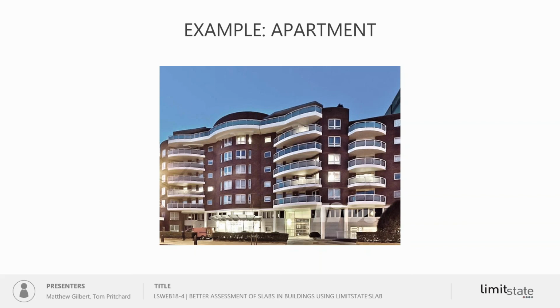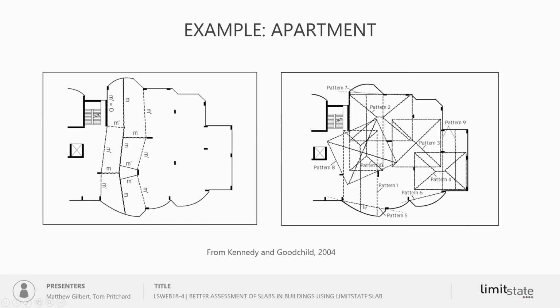And then the last example I'm going to consider is one that was actually considered in the Concrete Centre guide on yield line design some years ago, I think 2004. This is an apartment block in London with quite a complex geometry for the floor plate. And what they did is design that floor plate using yield line methods. In that case, what it meant was they had to consider a series of yield line patterns.